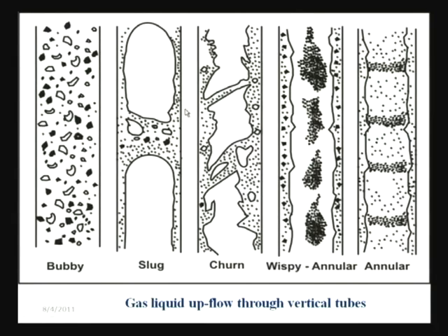Now, when it meets, naturally in this confluence a good amount of vorticity is produced. Due to this vorticity, some amount of air is sheared away from the surface of the bubble and tends to aerate the liquid slug beneath. Now, usually the aeration is more just below the bubble as compared to further downwards.